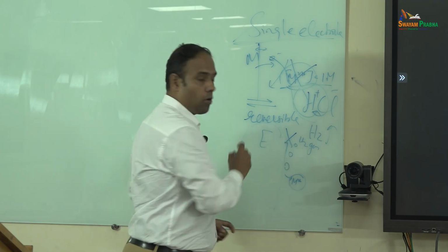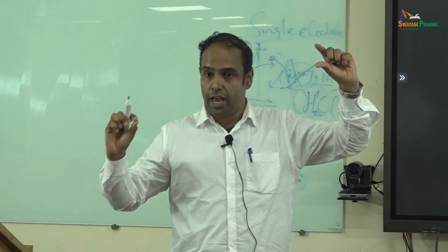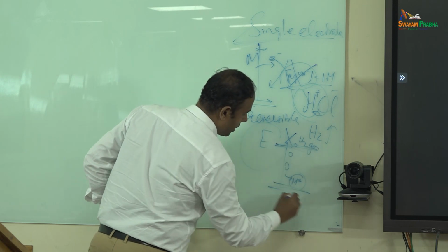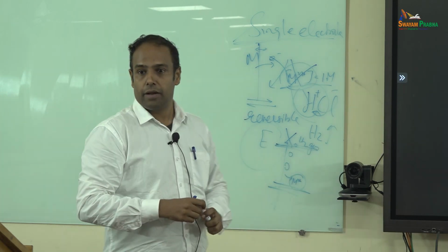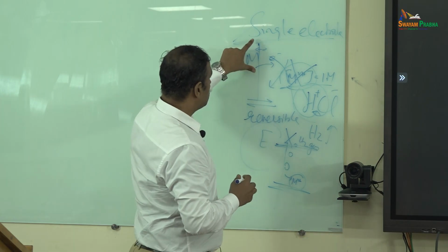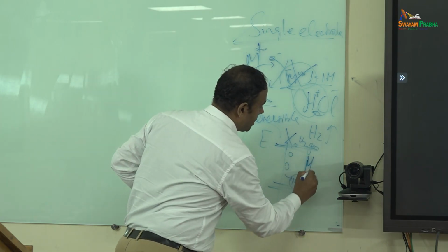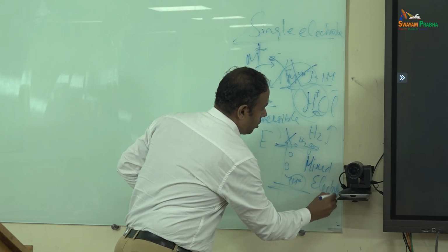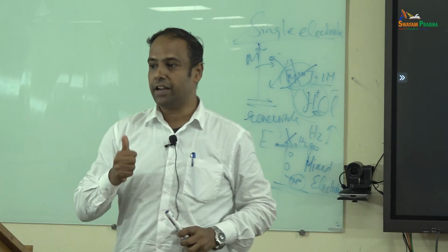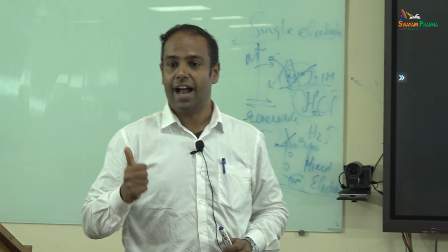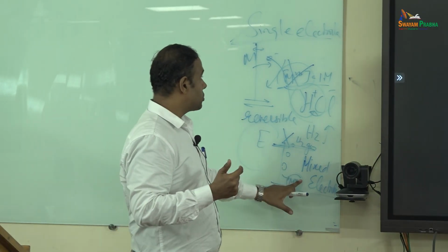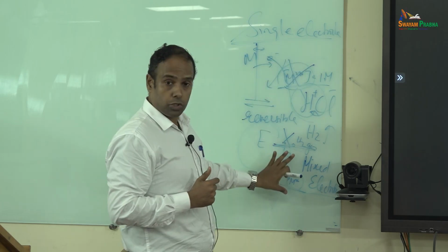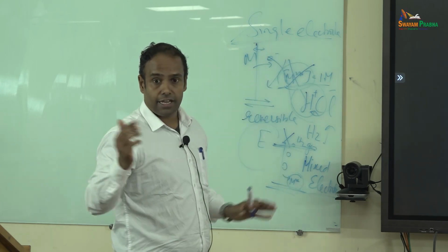So this now is two independent reactions at two different conditions becoming a single potential, and this is what we call a mixed electrode. So, the corrosion process which we talk about is often irreversible in nature, and it is a mixed electrode, but not a single electrode. Okay. This has its own potential. That is the example he said.